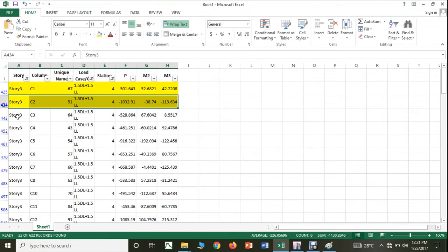Since the problem that we have taken was the very first problem, I didn't design the columns separately. When we go up with the next problem, definitely we will design each and every column by looking like this, biaxial or uniaxial or axial. But as of now in this problem, since it is a first problem, I have designed all the columns as uniaxially loaded columns, that is one highest moment and one load.